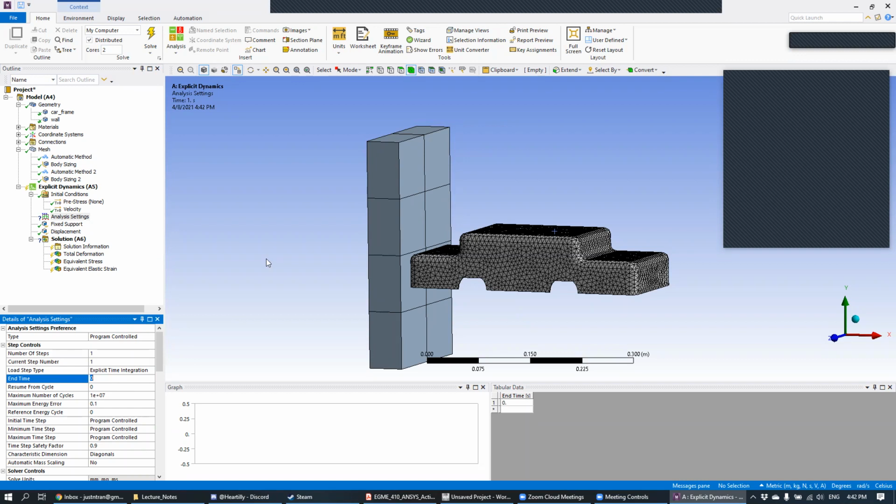Right? And so you want to set this end time such that you capture all the physics that you want within your simulation, right? And so you don't want to set this too short such that it basically ends before the crash actually happens, right? And so you don't want to set this thing to be too short, but you also don't want to set it to be too long either, right? Because if you set it to be too long, and so say you set this to be 10 minutes, right? What you're going to be simulating basically is the car is going to hit the wall, and it's just going to sit there for 10 minutes because you decided to run it for 10 minutes, right? And then for that entire time, your computer is going to be running, Ansys is going to be running, and your computer is going to be very upset with you because it's going to be doing a bunch of work for nothing, right? And so you want to set it kind of at the sweet spot where you capture all the events or all of the physics that you want to capture, but you don't set it to be too long so that your computer is kind of churning for nothing.